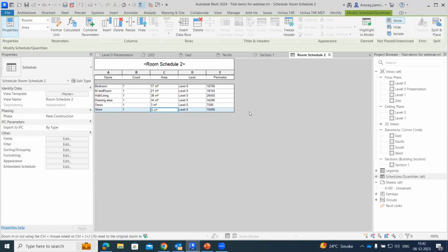So in CAD, we always used to have these tables inserted. Then we were writing by creating the boundaries or enclosed boundaries or polylines. We used to create those areas, type AA, enter, O, enter, and then we take out particular areas, and we write them onto the schedule box. So this automates our process of working and saves a lot of time in that particular process.